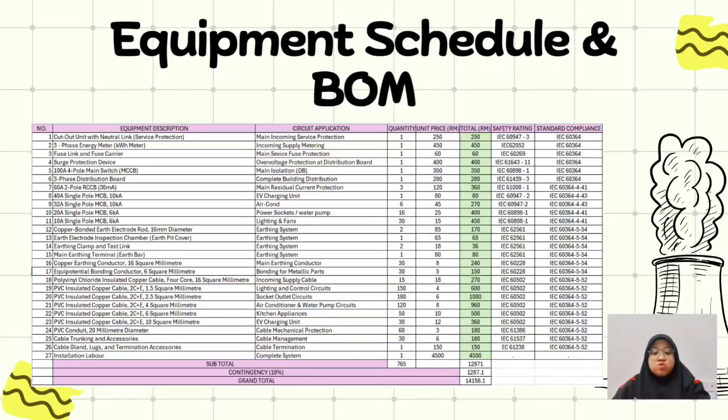Okay, next, we specify different sizes based on the load. For example, for the EV charger and large ECO unit, we allocate larger square millimeter cables. Although these are more expensive, they are essential to prevent overheating during long hours of EV charging. We're designing the system for the long haul, not just a couple of years.